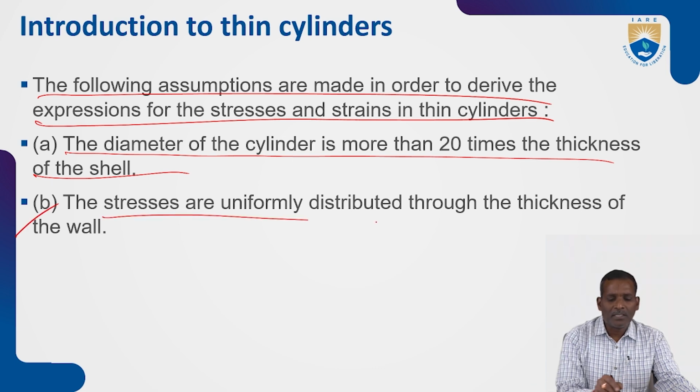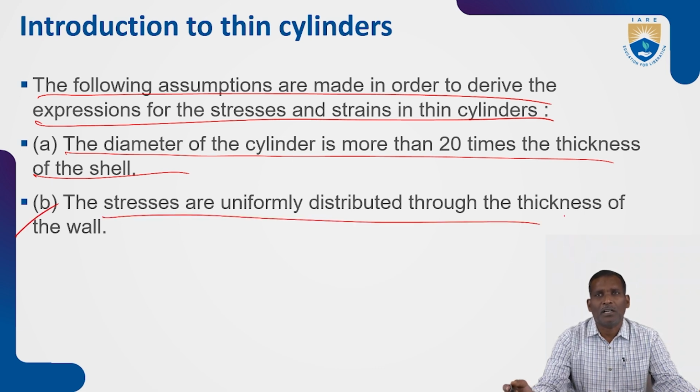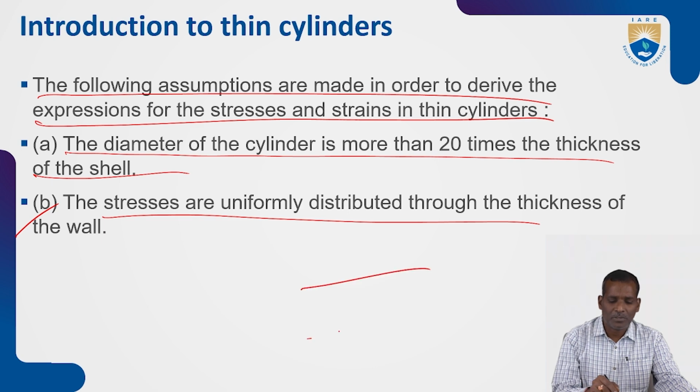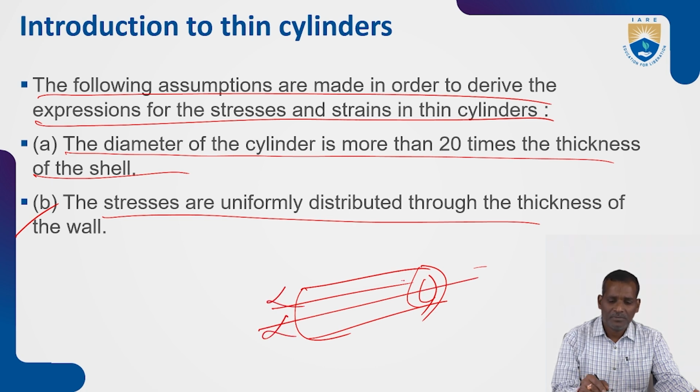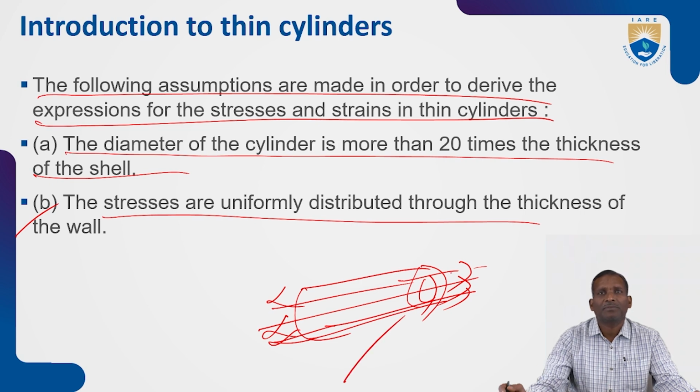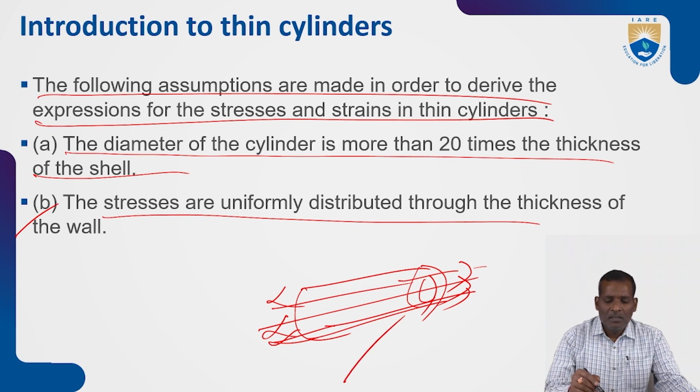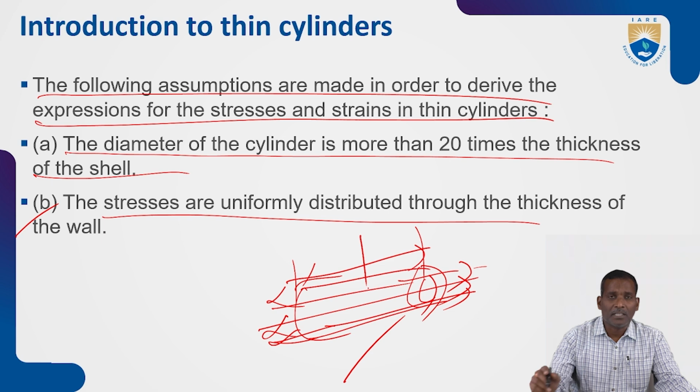Two, the stresses are uniformly distributed throughout the thickness of the wall. Whatever stresses are developed inside the cylinder are uniform throughout its thickness and along its length.